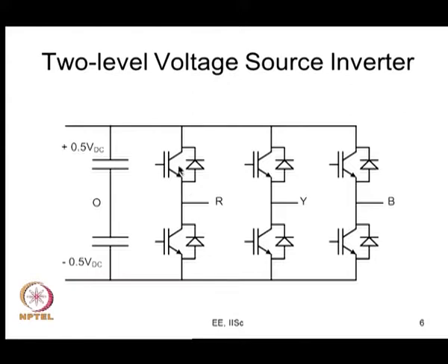If the transition is from transistor to diode, there is no delay, the switching is as per schedule on time. But if the transition is from the diode to the transistor, then there is a delay in the voltage level changing. Anyway, we will look at it shortly.